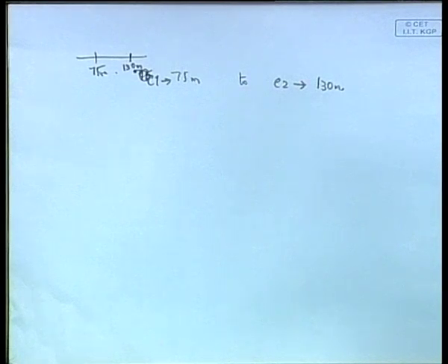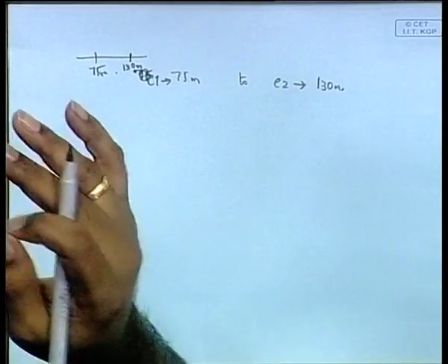So here we are adding this 600 tons. 600 tons is added. No, it's not like that. It's actually told distribute 600 tons. It means some of that weight is added at 75 meters and some of that weight is added at 130 meters. The center of mass of that 600 tons should be 15.31 from the center of flotation. Yes, that is what they have done.